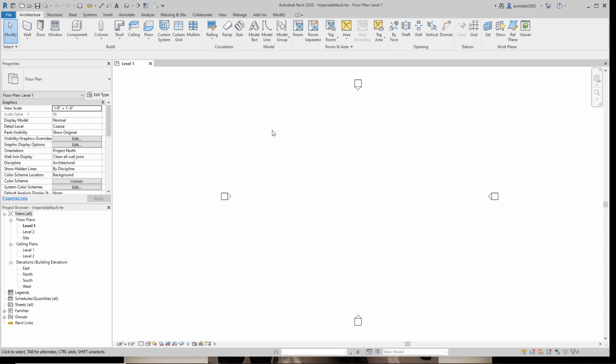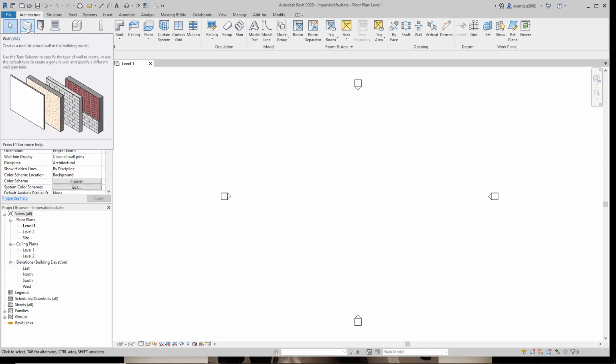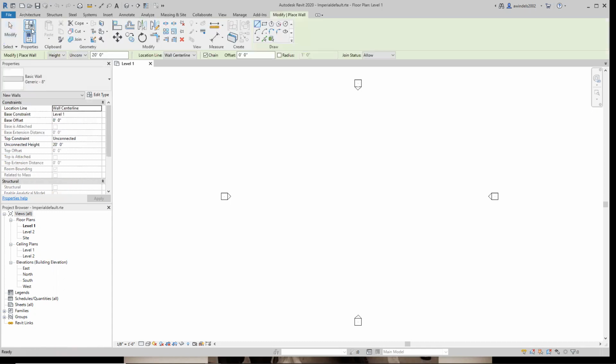So let's get started by making our first element in Revit on page 4 and 5. We're going to make it just a wall. You notice here when I hover on it, a lot of videos show up. This is very helpful to learn commands, to figure them out. WA would be the alias command. We'll get into more of that later. We can customize the alias commands. Some are already default to Revit. Let's left click on it.